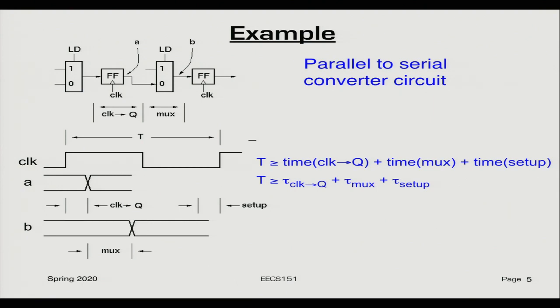right? And then we've got this constraint here that the new value into the flip-flop has to change before the setup time here. And you can see in this case there's plenty of margin, right? In fact, there's extra slack in this circuit. We're clocking it slower than we could. If we wanted to, we could actually, in this case, make the clock period smaller, and we'd still be fine, because we have this much extra time here. Right?